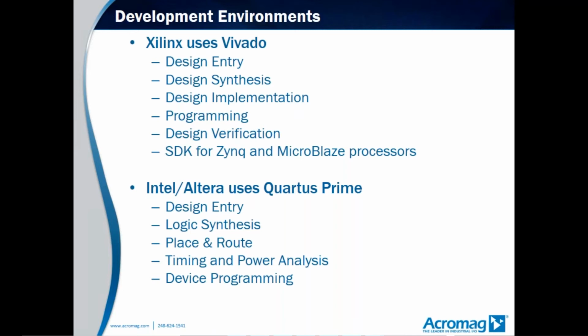Intel and Altera use what they call Quartus Prime, and it's very similar in that you do design entry, logic synthesis, place and route, and then timing and power analysis, and finally device programming. In part 2, we will get into the details of the Xilinx Vivado tools as we go through an example design.